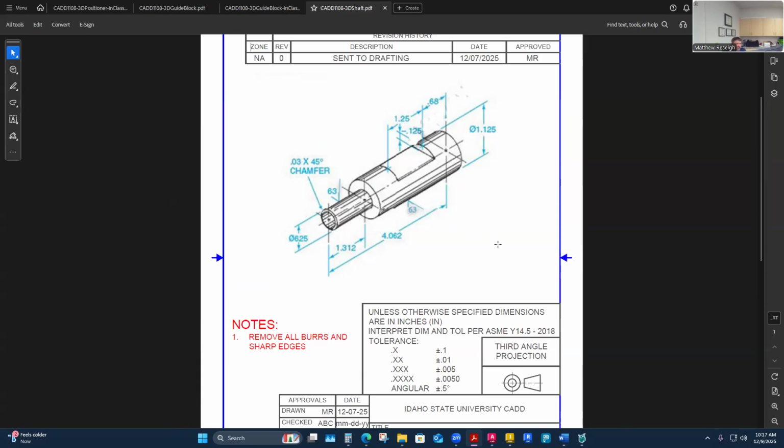So really, this is the one that kind of breaks the rule on the width being the longest width in the front view. On those blocks, I did put the width in their longest view in the front view. Here, I'm going to kind of break that rule, and my front view is just going to be looking like circles, and my right side view will be the shaft. And I think some companies may tell you to do it otherwise. That's fine, whatever they say, which one on a shaft they want to call front versus right side.